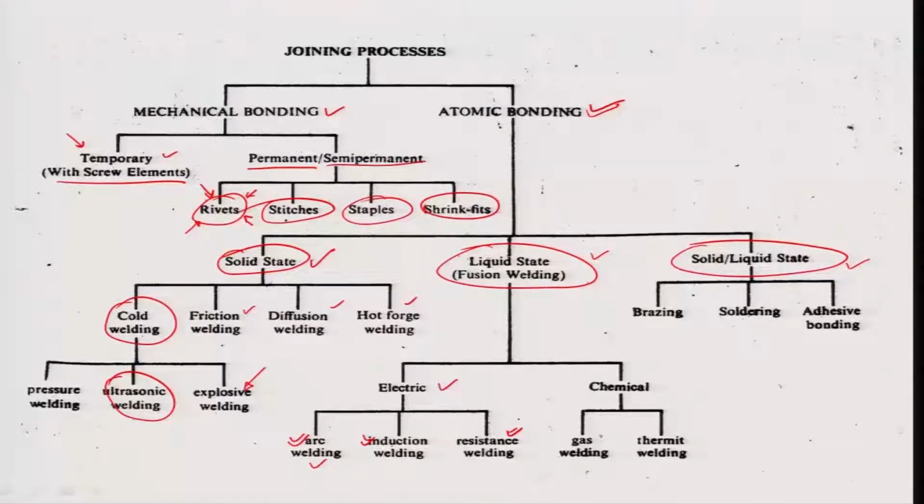The other forms of liquid state welding are those where the source changes from electrical to a chemical source. It could be either a hot flame produced by a gas, or by the transition metal oxides and aluminum fuel particles, together known as thermites. And the heat source in a gas welding typically is an oxyacetylene flame, which causes filler material to melt and go into the two sheets, and then it re-solidifies to formulate the weldment.